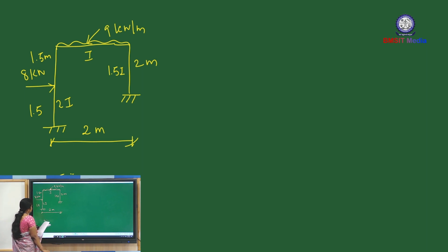And second one is boundary condition. So the boundary condition is also the same. And third one is unsymmetrical shape. Yes, it is definitely unsymmetrical shape only. About this vertical axis, this is a different shape and this is a different shape because the height of the column is different here. So this type of frame is subjected to sway only.